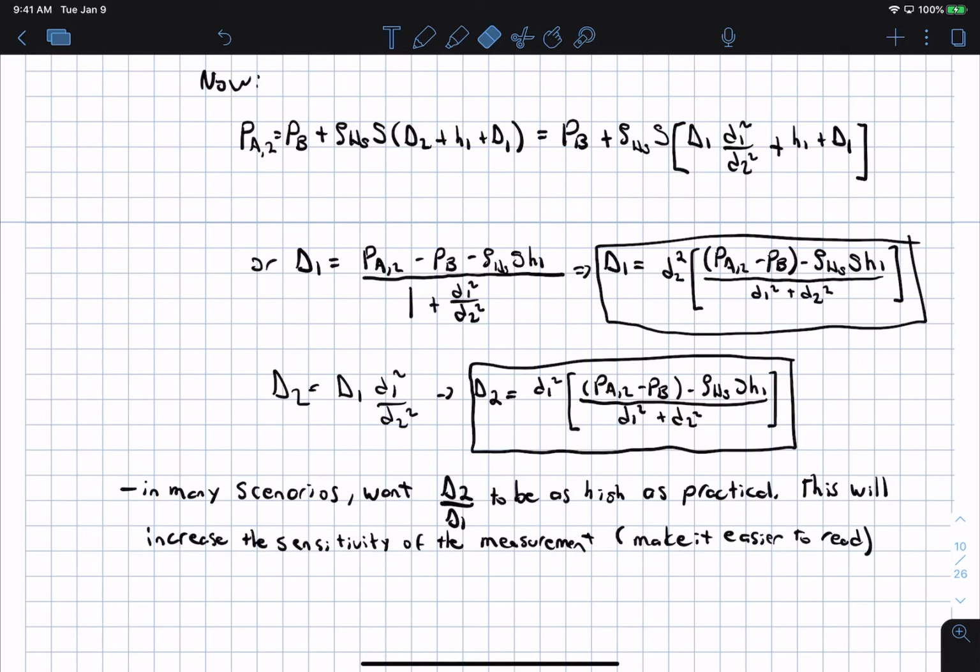So for instance, if you're in a plant and you're monitoring, I don't know, a water pressure in a pipe, you don't necessarily care what the absolute pressure is, but you want to know if there's a pressure excursion. And so you want a nice gauge that can just tell you how much the pressure has changed.